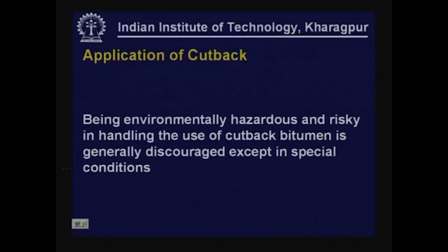But being environmentally hazardous, and considering the risk in handling this material because of the volatile material that is there, the use of cutback is generally discouraged except in special conditions. So, nowadays the use of cutbacks, especially in highway projects, is not permitted unless special conditions persist.